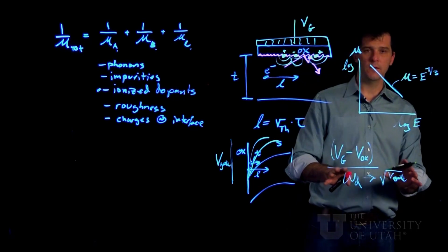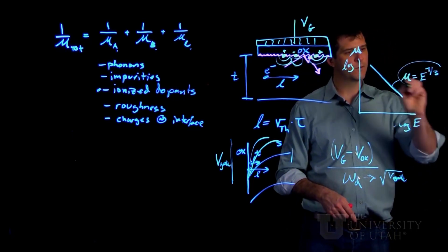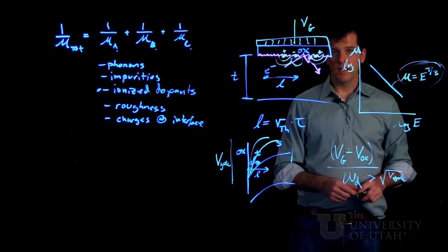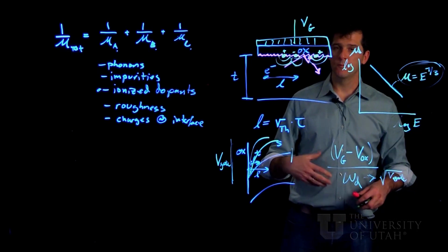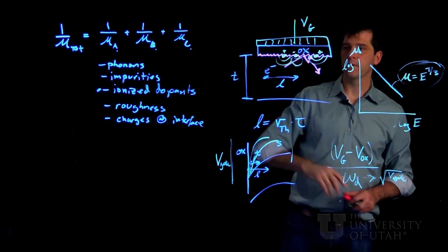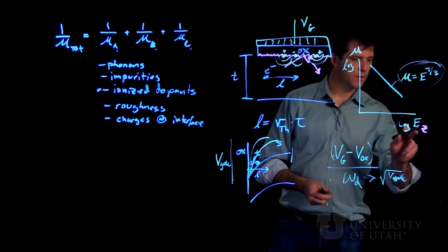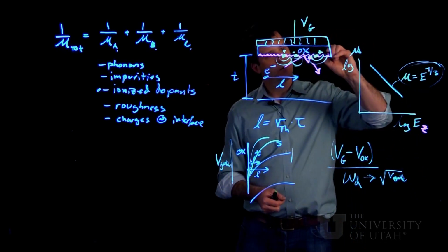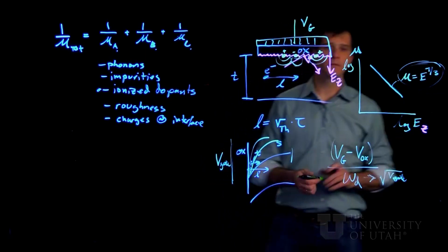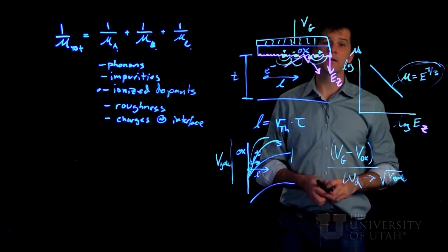So there's a complicated mathematical form which leads to the empirical minus 1/3 law here. Other things can happen which bring us out of the mobility regime. Now this E field here is the E field along the Z direction, which has to do with controlling the depletion width and the inversion charge in the channel.